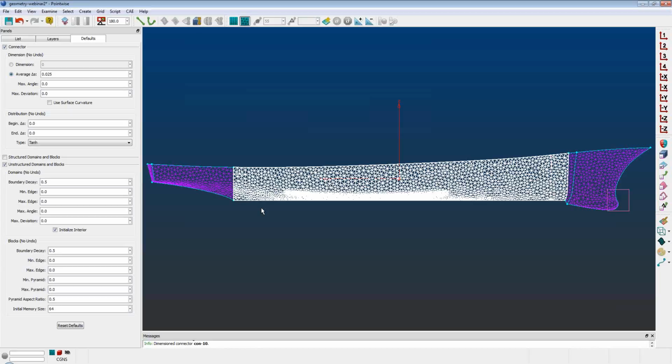This actually kind of leads back to my point about doing the solid modeling. When you're reusing the geometry many times, you can create that model, give it a name in Pointwise, and also give names to all the subsequent quilts within that model. Then you can redo that process and reuse all those names, and Pointwise should snap to those quilts and those models.